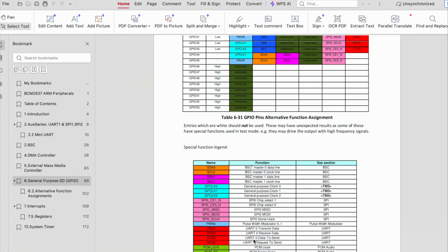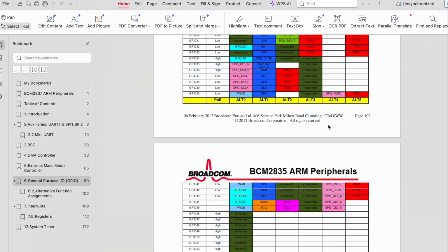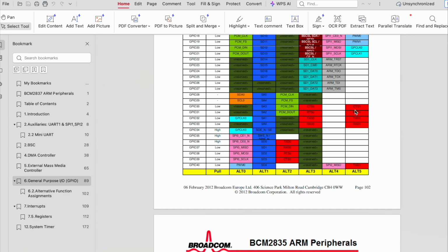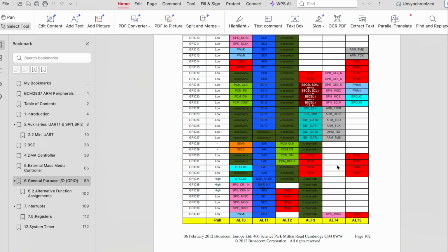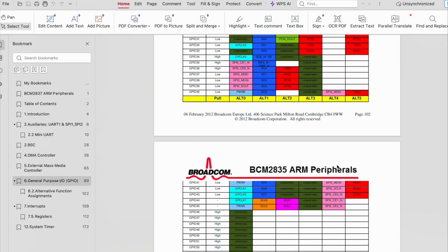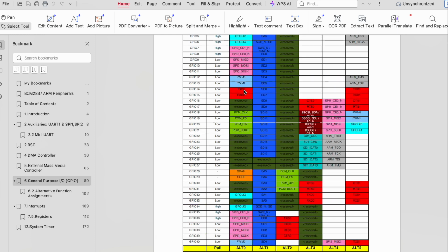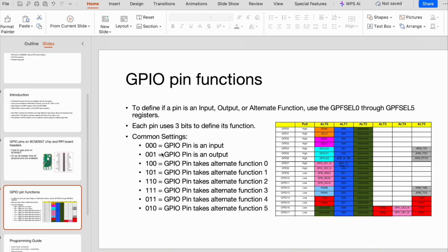But these functions are just to clear, so we don't have to count them separately. Okay, so other pins can also be used. Sorry, my bad. I think only 2 UARTs are there, TXD0 and TXD1. The rest of them are just other GPIOs you can use instead of that. Okay, so these are the total 6 functions which can be selected by using these 3 bits.